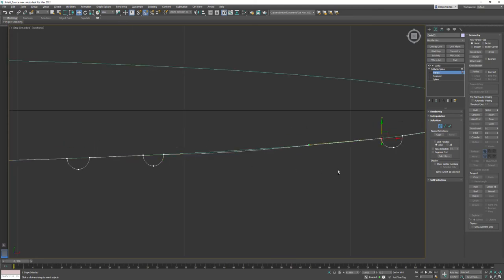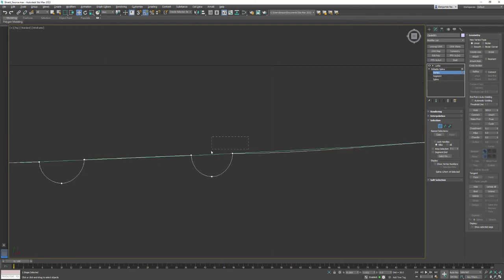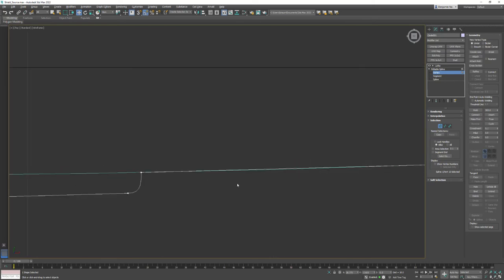Maybe instead of doing that, what I'm going to do is just go into Refine and click and add a point there. And then I can just move that point to where I want it. And just make sure it's a Bezier point. So I can adjust it, adjust this angle, take this one. I guess it's snapping them to make them a straight line is what it's doing.